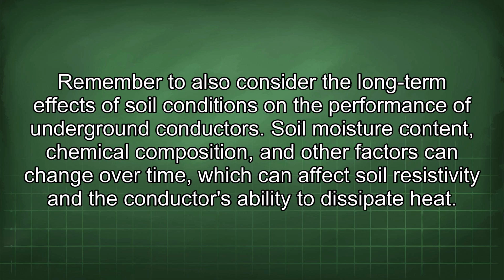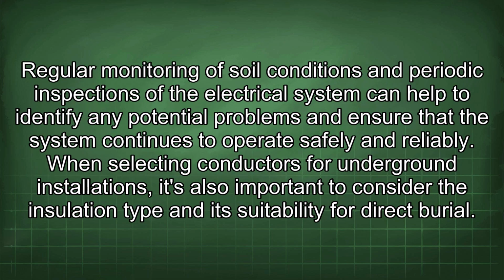Soil moisture content, chemical composition, and other factors can change over time, which could affect soil resistivity and the conductor's ability to dissipate heat. Regular monitoring of soil conditions and periodic inspections of the electrical system can help to identify any potential problems and ensure that the system continues to operate safely and reliably.